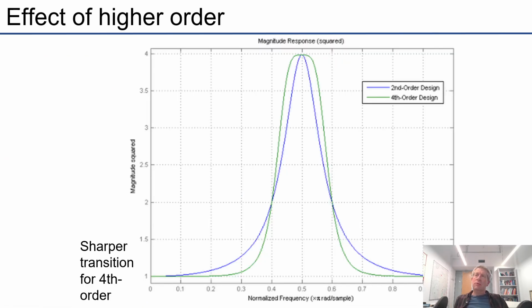High order filters give the sharper and sharper ones, where you get closer to that extreme ideal behavior, like a bandpass filter that is exactly 0 and then jumps up to being exactly 1 and then back down again. Now you need to go to very high order filters to get anywhere close to perfect behavior, but it is true that the higher the order, the sharper the transition.